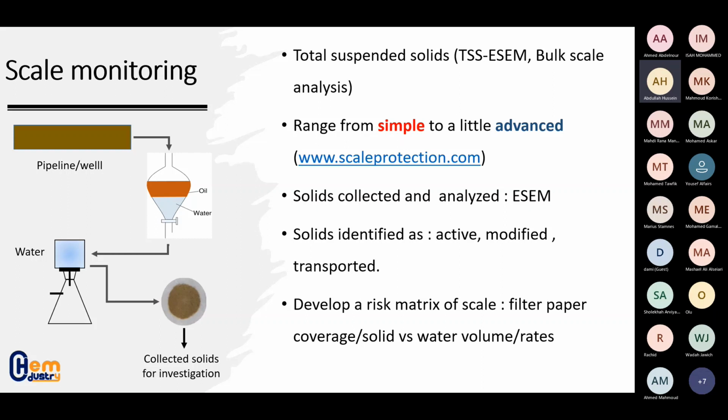It's called TSS-SEM, or also called the bulk scale analysis. There's a company that can provide this service. It's called Scale Protection. What they do is they collect a sample of the fluid and filter the water. They take the filter paper and assess the problem by the surface coverage, and then they determine the solids composition using the SEM.